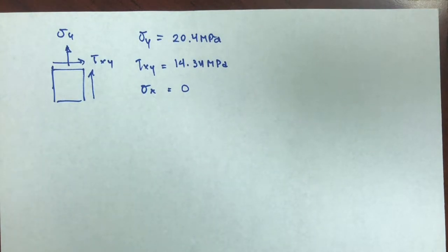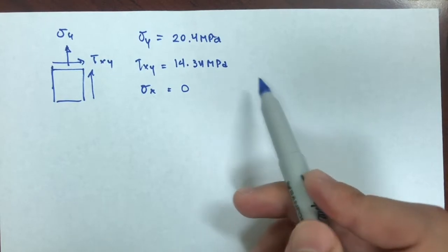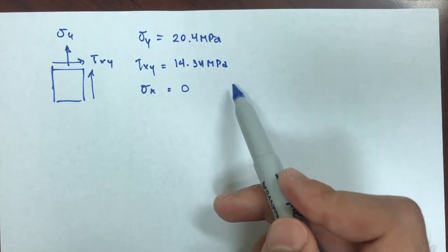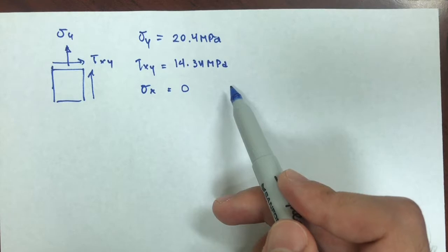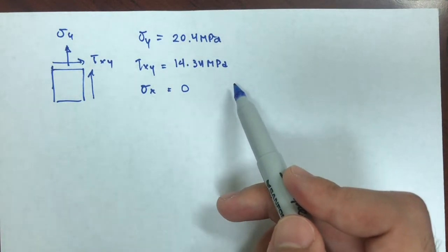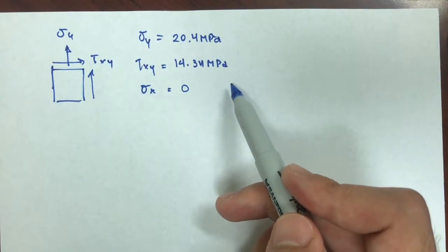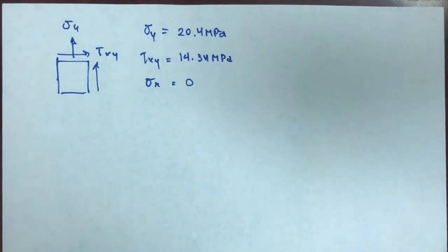We don't need the Mohr circle, so basically just by having these we could calculate where the center is, then add a radius, and with those I can find the principal stresses both for the maximum shearing stress and the maximum normal stress. But let's do the Mohr circle just to practice that a little bit.